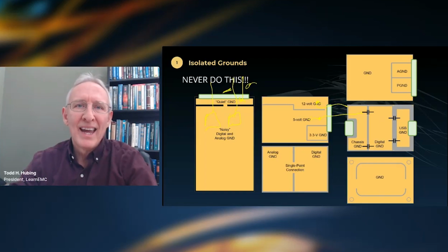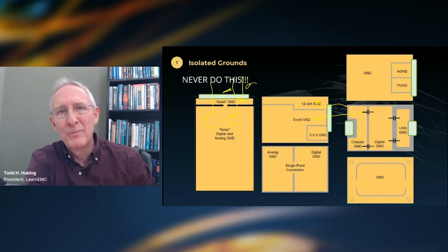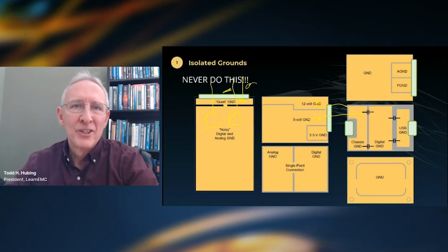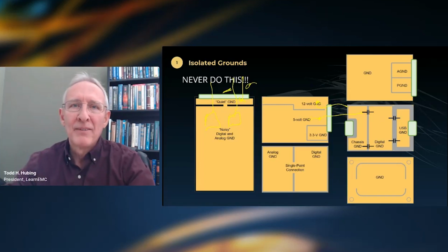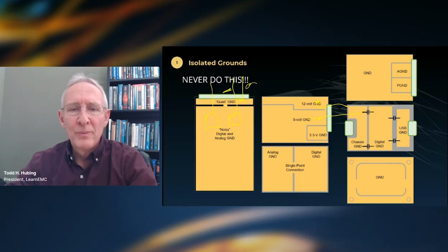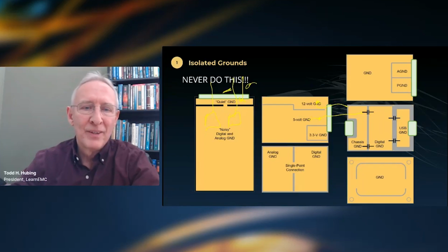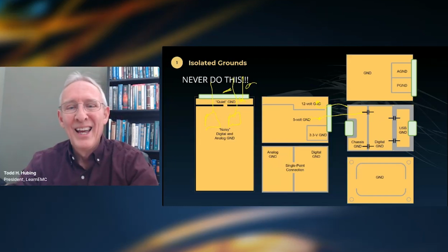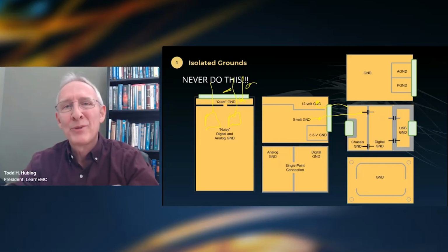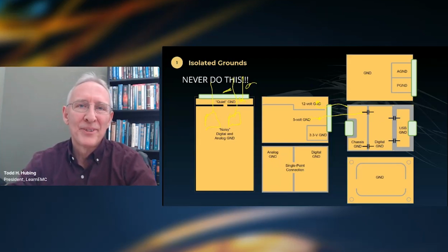Most boards I see have that today. This used to be much more of a problem if you back up 10 years or more. We saw a lot more of these split planes. People have, in my experience, largely recognized this is always a bad idea. Why do I show it, or why do people do this? Because actually, if you look in some EMC books, all of these examples were taken from books or application notes.